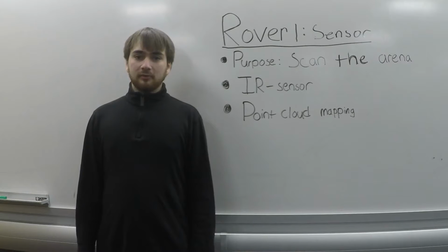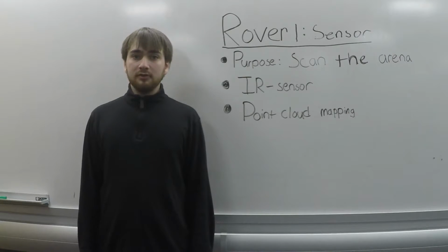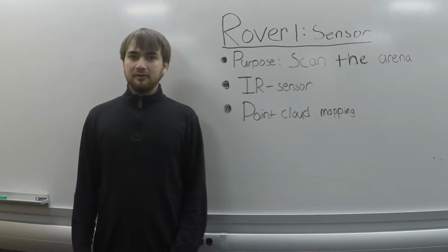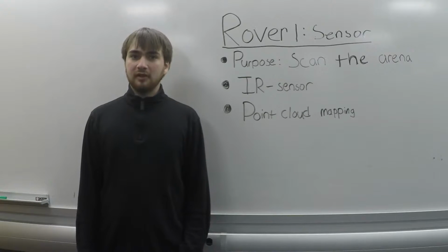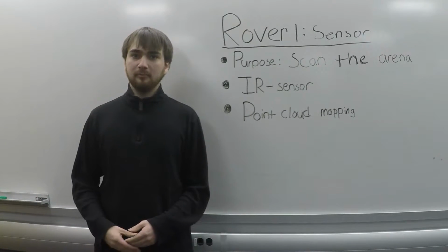My module had 3 IR sensors connected to it, 2 on the front and 1 on the left side. The 2 on the front allow the rover to avoid obstacles that were in front of it and turn until it had finished clearing the obstacle. To use the IR sensors, I had to get useful data out of them. These IR sensors were plugged into a 5-volt source, and they produced an analog output that corresponded to the distance that was in front of them.